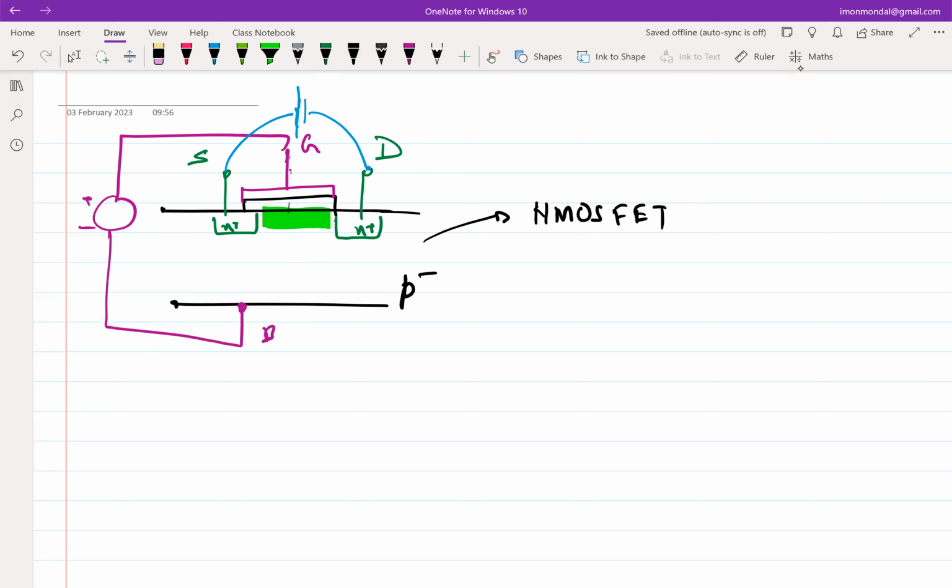I also made a further point that in the presence of these drain and source dopings, which are N+, you may as well get rid of this body terminal, you may as well refer the gate voltage to the source terminal, because now you have a locally placed high concentration of electrons, right? When there is a need for electrons, these N+ regions can supply the electrons. You did not wait for thermal generation to take place. So which essentially means that I can simply refer everything to source.